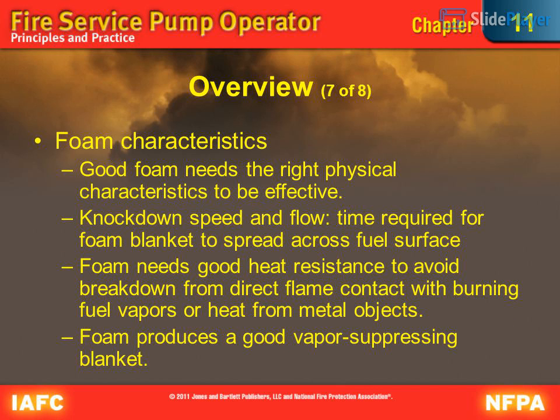Overview, 7 of 8. Foam characteristics. Good foam needs the right physical characteristics to be effective. Knockdown speed and flow, the time required for the foam blanket to spread across the fuel surface. Foam needs good heat resistance to avoid breakdown from direct flame contact with burning fuel vapors or heat from metal objects. Foam produces a good vapor suppressing blanket.